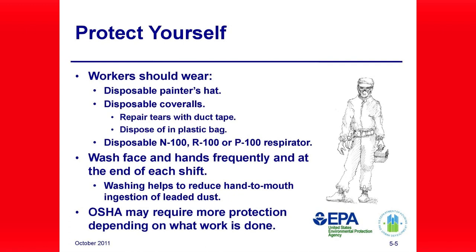The protective equipment listed above is meant to show what is needed during activities that disturb lead-based paint and lead-contaminated dust. Depending upon work practices used, OSHA rules may require employees to take further steps to protect the health of workers on the job. OSHA provides additional information on working with lead in their safety and health regulations for lead in the construction industry, 29 CFR 1926.62.